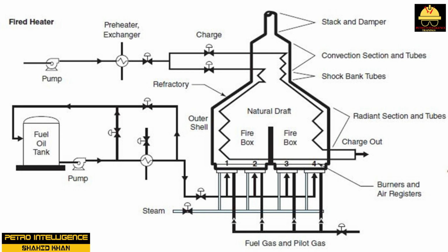Adjustments to the airflow rate are made at the burners and the stack damper. The floor of the furnace has a 6 inch layer of heat-resistant castable, capped with high-temperature fire brick. Some cabin furnaces have a bridge wall that equally divides the firebox. A split-flow tubing arrangement exits the upper convection section as product flow drops down and into the hotter radiant section.